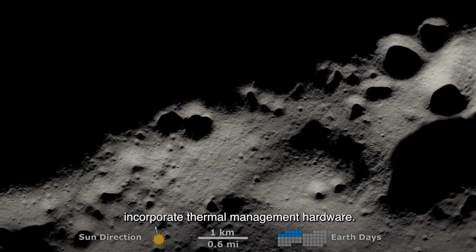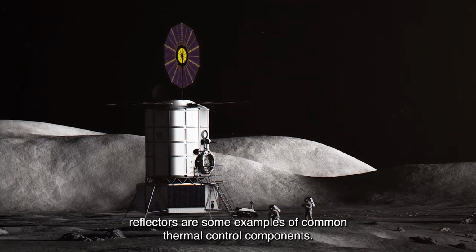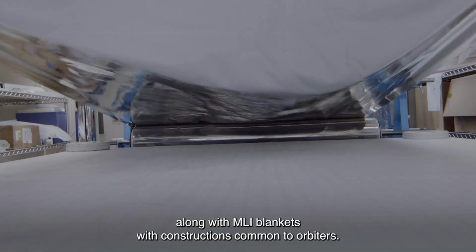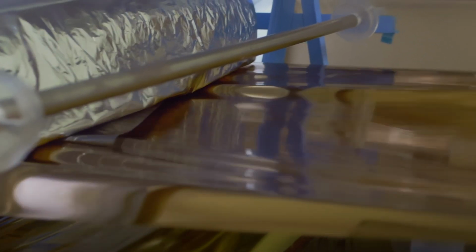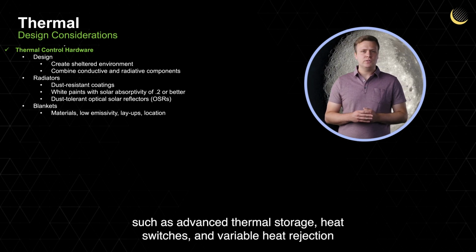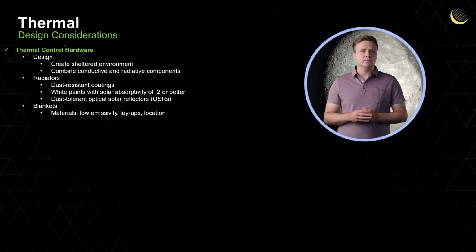Whether the system is targeted for lunar day or night operation, lunar system designs must incorporate thermal management hardware. Dust-tolerant radiators and optical solar reflectors are some examples of common thermal control components, along with MLI blankets, with constructions common to orbiters. Other more complex thermal technologies, such as advanced thermal storage, heat switches, and variable heat rejection radiators, are active research areas envisioned for lunar night survival.